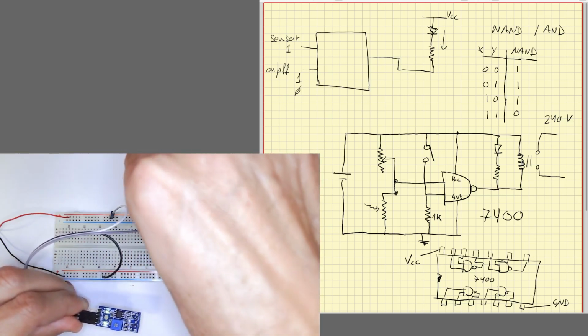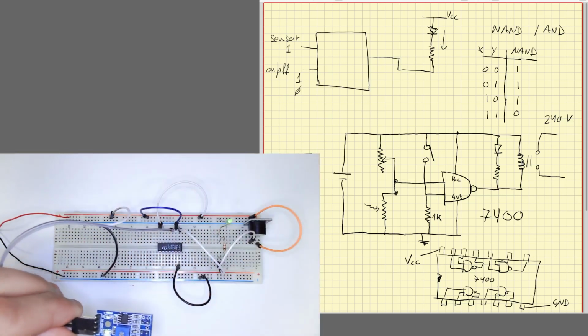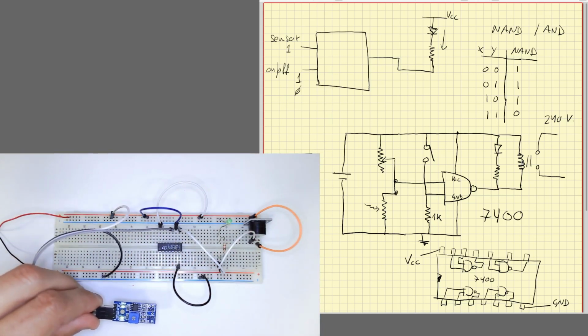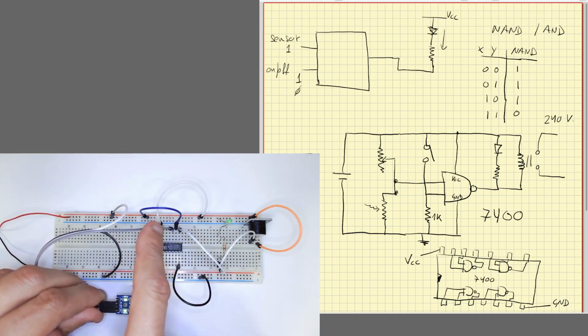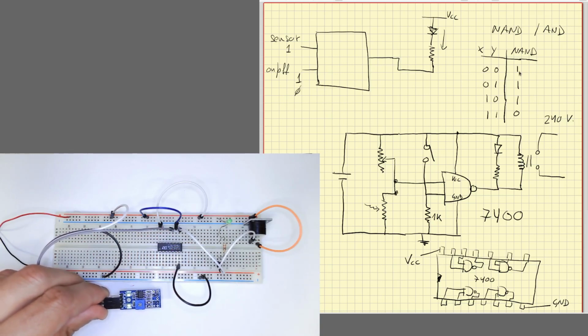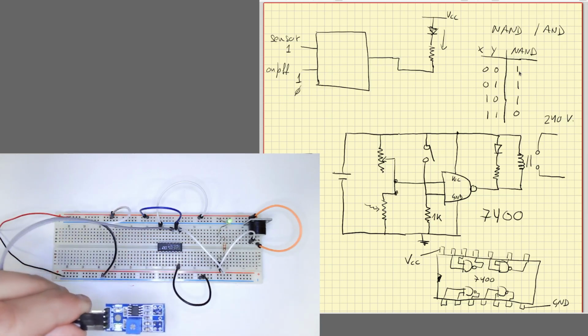Now I connect my circuit again, and you see that, okay? You know it's active low. It means it's in proximity with something. The output is 0, so the output of our gate is high, and we detect actually in this configuration when it goes out of the proximity.